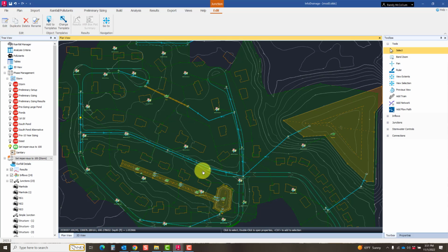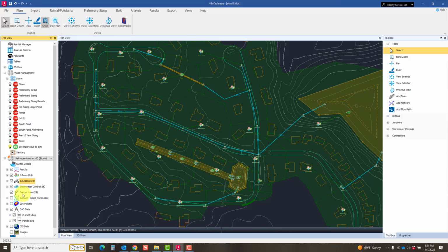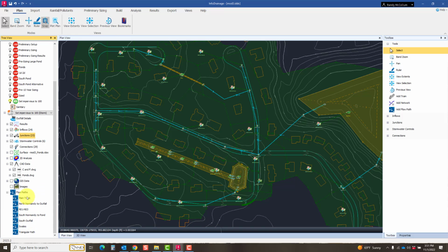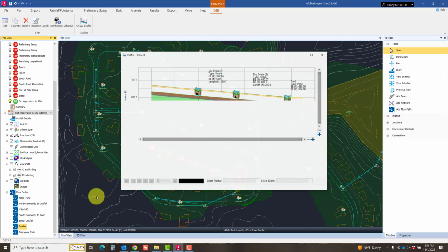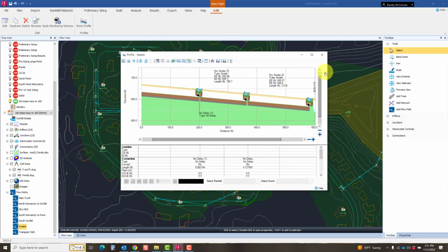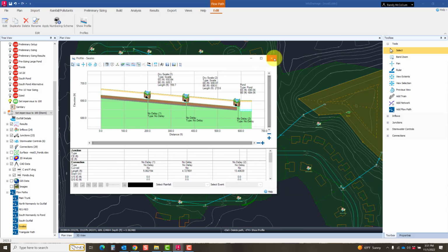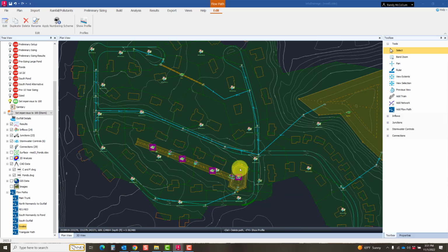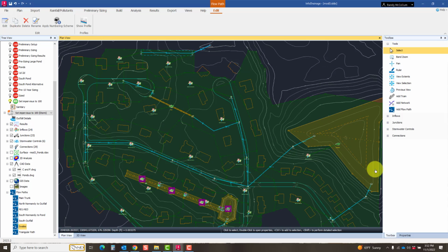Now, I have everything configured. I have a number of flow paths set up, so you could see not only along the main trunk, but you could see along other lines. I've set up a number of swales as well as a pond here that I can see in profile, with a number of check dams set in between to fill up each one of these areas and take advantage of infiltration to limit the footprint needed for my pond. I have pipes, I have triangular channels, you name it.